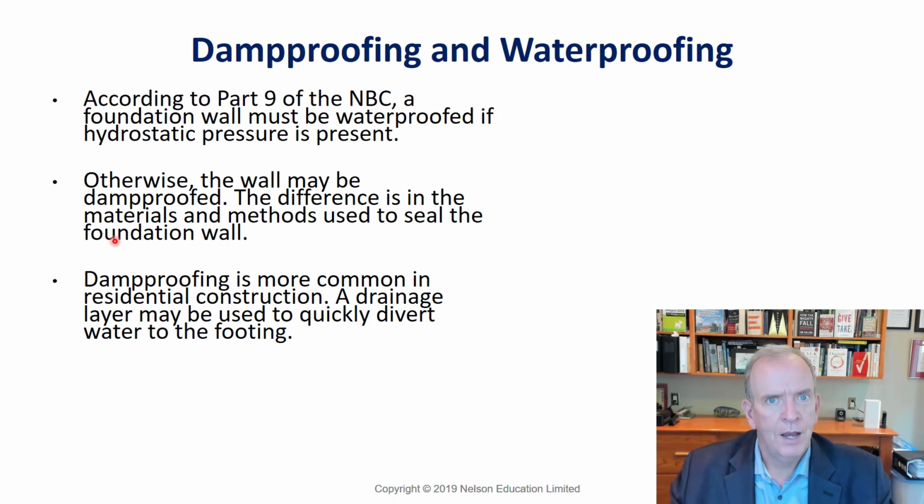You have an idea that hydrostatic pressure would be present if you're excavating and your excavation starts to fill with water. Then you know that you're digging below the water table, you've hit an underground stream or something of that nature, and that would mean that you're going to have to waterproof your walls. If you're excavating and the excavation is not filling up with water, then that's a good indication that that's not an issue in that particular case. Of course, there are different areas where you can have different things occurring during different times of year, and so some of those designations might come into play too that might require you to waterproof.